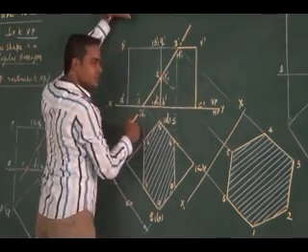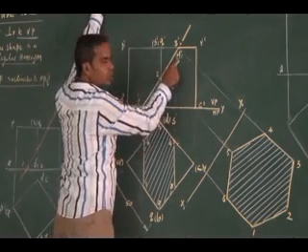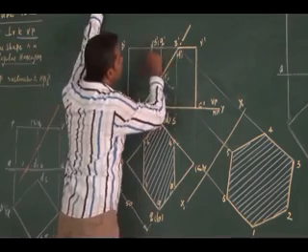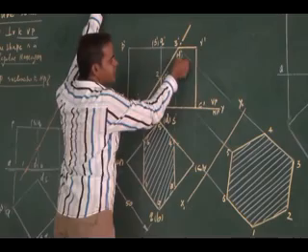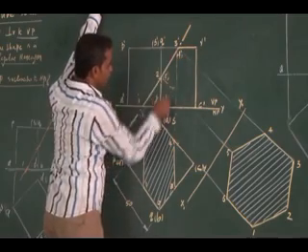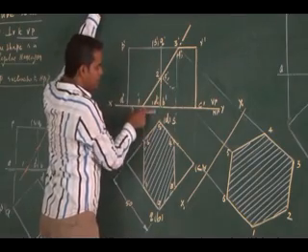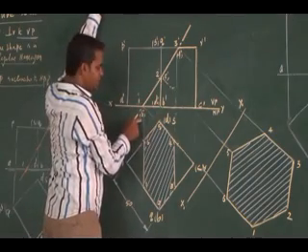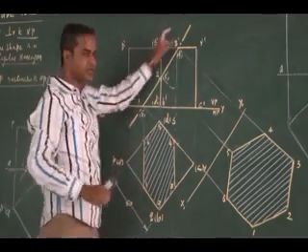Then you come back in the same manner along the cutting plane, looking for the hidden cutting points. SR, a hidden face edge, cuts, that is cutting point 4, and hidden vertical edge DS cuts, cutting point 5. Then the hidden base edge, that is 6 dash. So totally I have 6 cutting points exactly in the middle.